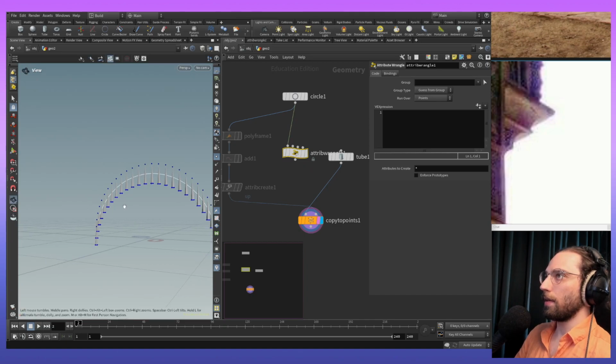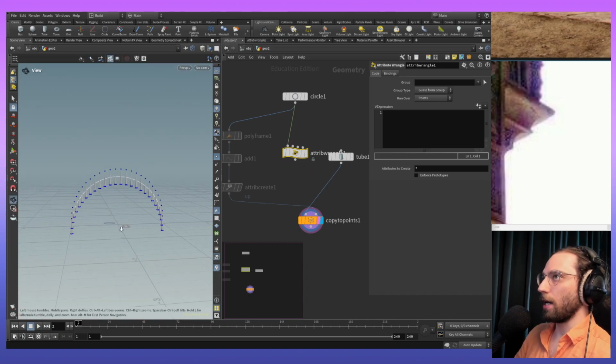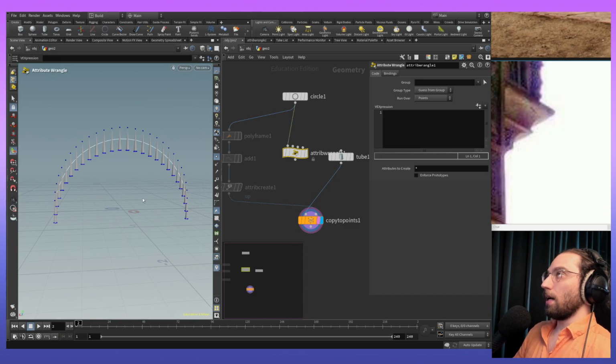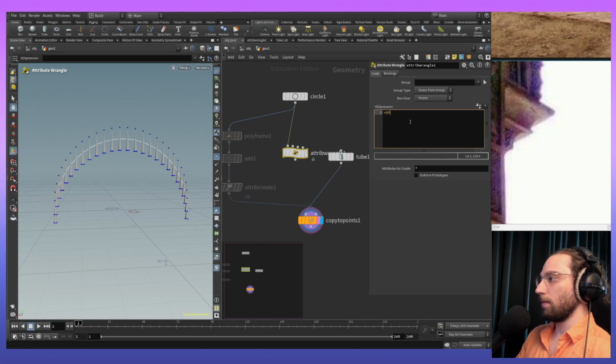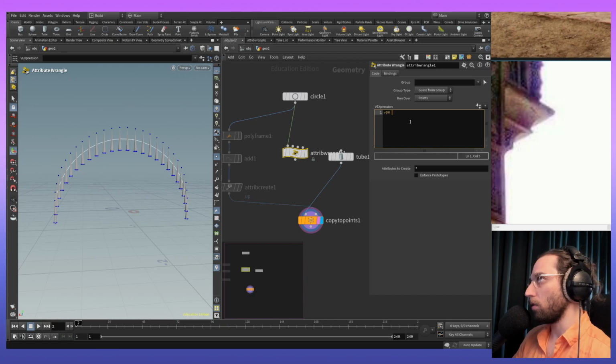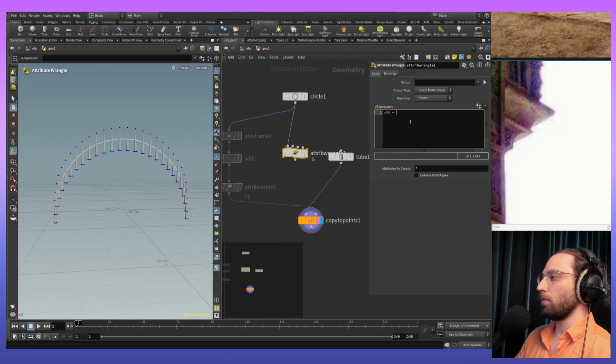And so the value we want to change and create is, first of all, we will announce a value that is the normals. So we will say vector at n. Now we created a vector value and it's called n, which goes to the normals in Houdini. And we are currently saying the value of the normal equals to the value of the position.